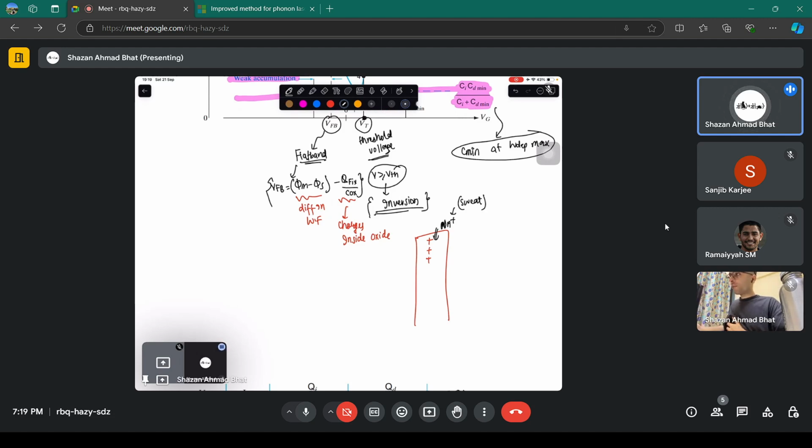That's why in fabrication you have to wear those suits to keep everything clean. If you are sweating a lot and you are touching the chip, the sodium ions and the potassium ions from your sweat will get diffused into the oxide, and they will stay here. They will stay here, sodium ions. And these are immobile, these are very tricky to deal with.